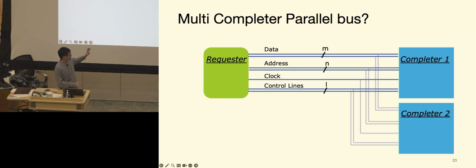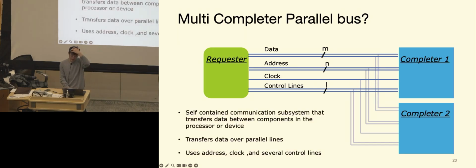And let's talk a little bit more about the control lines. Basically, the control lines are additional dedicated signals that manage and coordinate the data transfer between devices. They do not carry the actual data. Instead, they provide other critical information like the select pins, as well as other operational signals necessary for successful communication, like flags or ready.